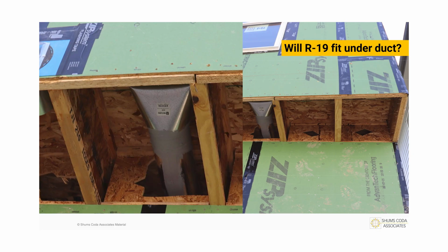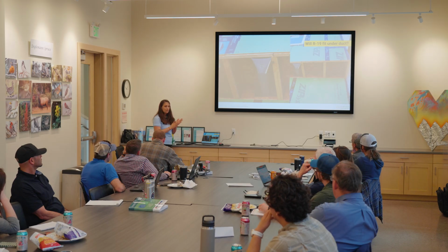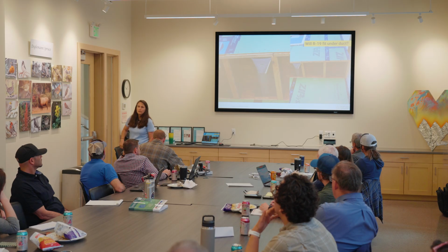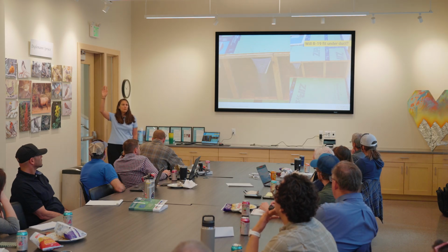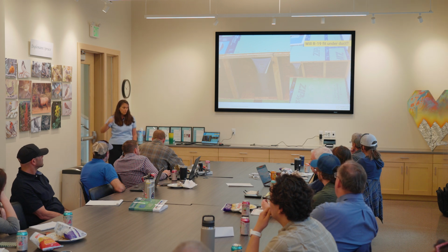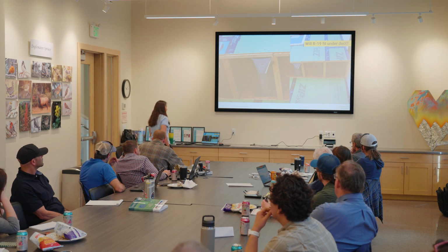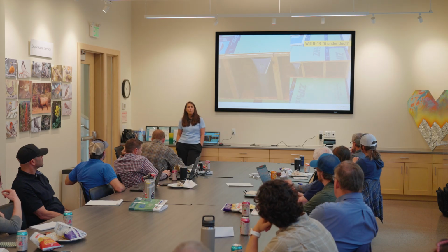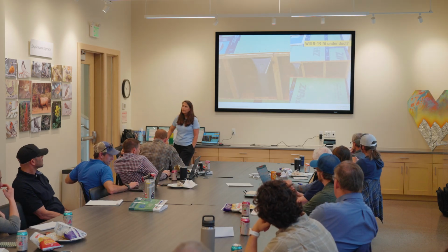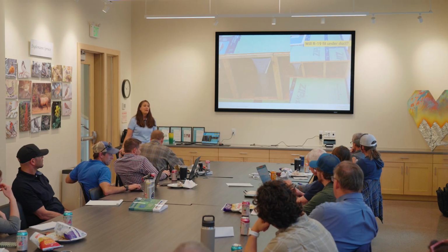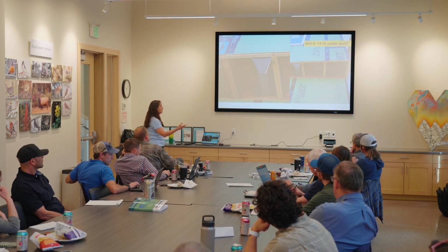Okay, I'm going to say most of you are correct. And you say, how can we all be correct? Well, how many of you thought of batt insulation or blown-in insulation when I asked you that question? Okay, so we know that that has about between a 3.2 and a 3.8 R value per inch. So that means what? 5.5, 6 inches is what we would need there.